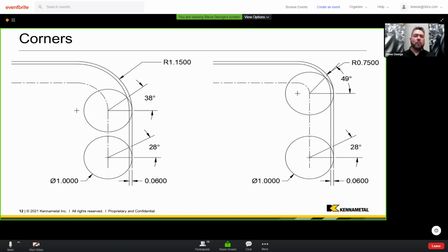And I just bring this up because sometimes people try a dynamic technique where they're used to using traditional techniques, and everything ran great, had tons of tool life, it sounded great, and all of a sudden it snapped. What happened? Well, when you've cranked up your conditions and you have, let's say, an interruption in terms of the path that changed the dynamics of the situation, that's when you run into a problem. So that's one of the biggest things, is to think ahead.